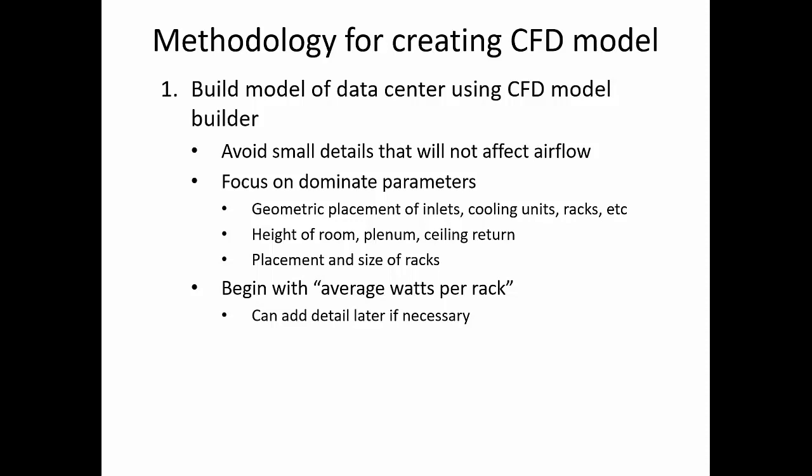And we typically start with watts per rack. This is another one. How much detail should I put in the rack? Well, you can always add detail later. Start with average because that'll tell you an awful lot about the general flow in the room and what's going on in the room, and you can always go in and tighten up the model later. But over-designing a model in terms of detail early on slows you down and doesn't allow you to get your arms around what's going on in that data center in terms of understanding how those parameters affect the overall design.